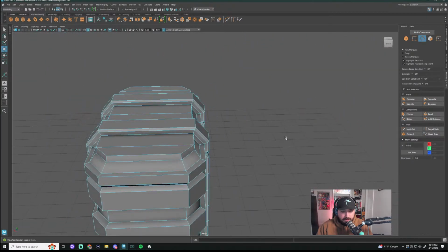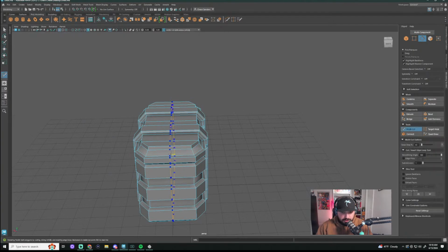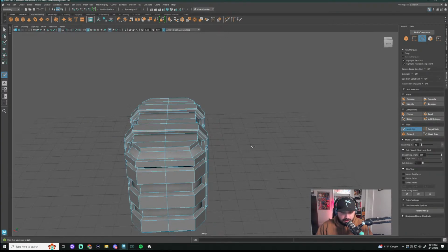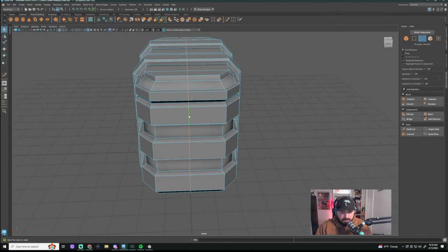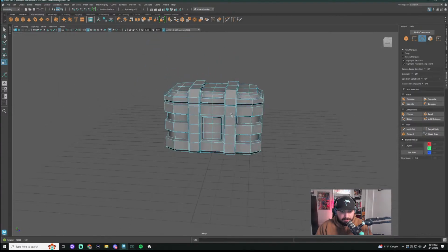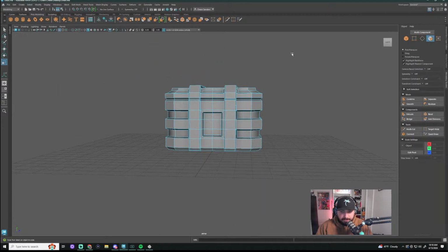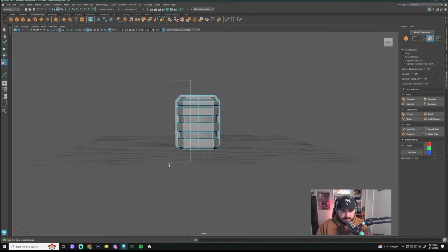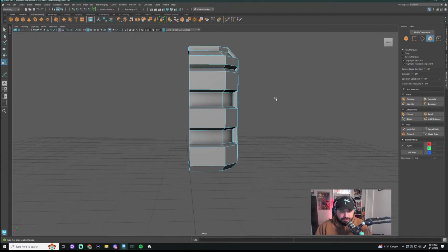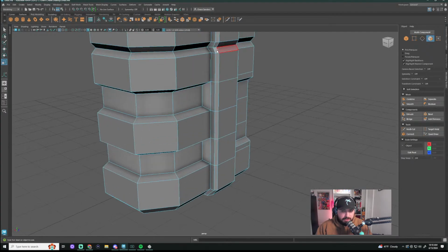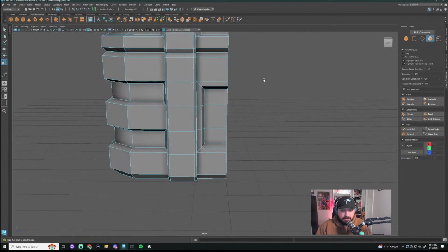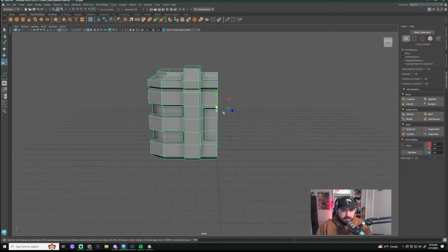Yeah, I like that. Okay, so I'm going to show you guys a trick, right? I'm going to cut 50% here. And since I like that front right quarter panel of the chest, I'm going to do something here. So I can delete half of my chest this way, right? Because this thing's all kind of symmetrical. And I can delete the back half here, right? Because I fixed this set of faces, right? So now that I've done that, I'm just going to take this guy and mirror him a couple times.